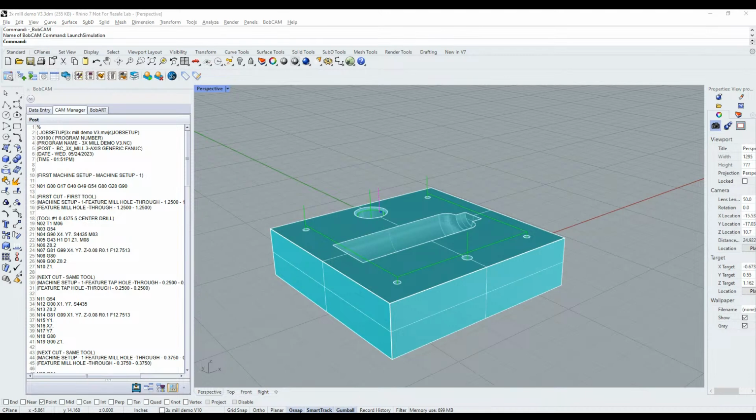where you can modify the G code. Everything's color coded here. Our comments are in green. XYZ moves are different colors, so we can easily find what we're looking for. Then we can go to the top and go to Tools. Go to Start DNC Transfer, where I can set my port number, set the baud rate, and set all the other settings for the machine to send or receive from the machine.